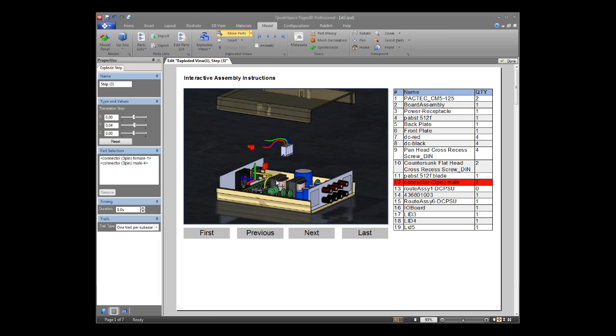One way to fix this is I'm just going to hit Control, and we're going to click on this yellow wire, which will add it to that step. And it should move with the rest of these guys. There we go. I think it just did an update there. And so we've added that to that step, and now that will fix pretty much our whole thing. So that was a new part number, and our exploded view didn't know what to do with that part number, so we had to go manually help it understand that.